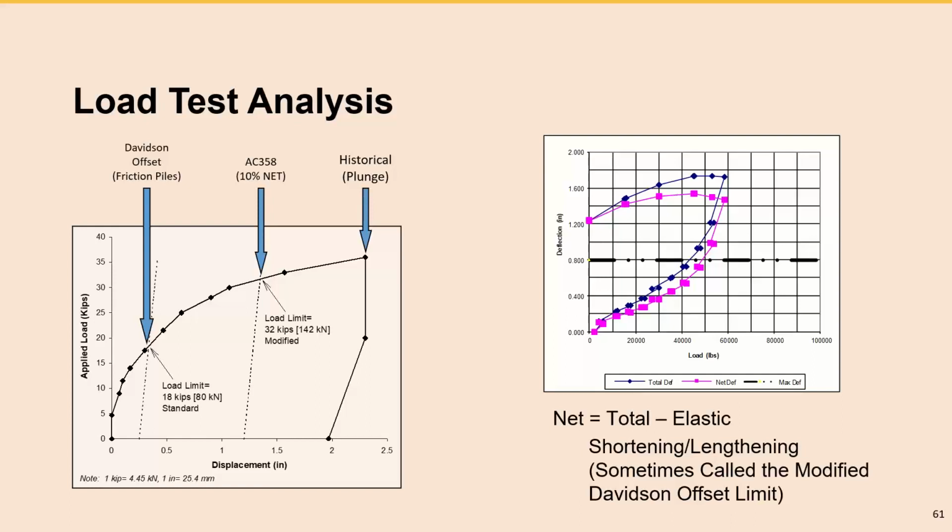helix. That means you need a net deflection equal to 10% of 12 inches. That means you need a net deflection equal to 1.2. That means the total deflection, depending on the length of that pile of course, is probably about 1.4 or 1.5. You stopped at 0.7. No, you keep going. Okay, so remember that these KT values are based on 10% net deflection.